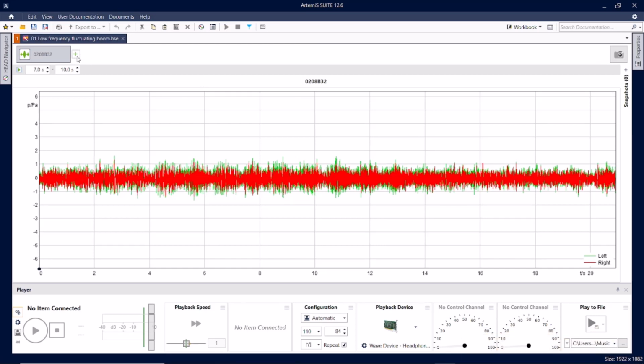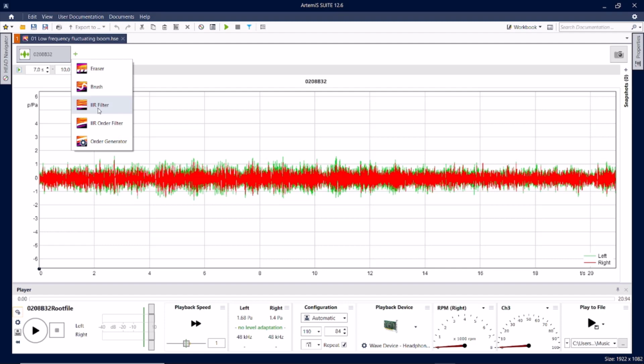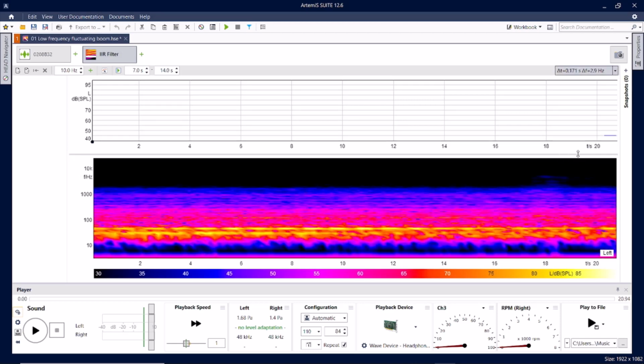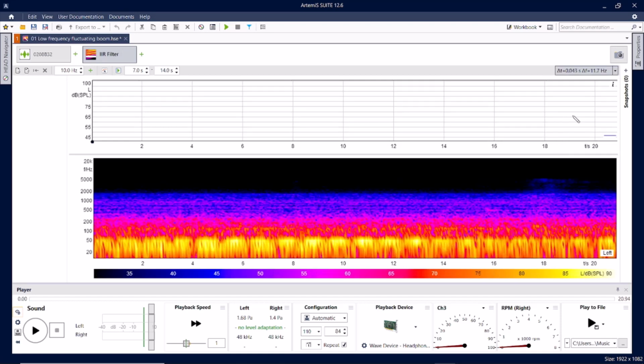So we select IIR filter. And we have not made a choice here yet about the resolution. We can see what that does. For example, we have 85 milliseconds time, 5.9 hertz frequency. Let's go to more frequency resolution. Now we start losing the time detail about the effect. Let's go to 43 milliseconds, and now we have not enough to really see what the frequencies are.